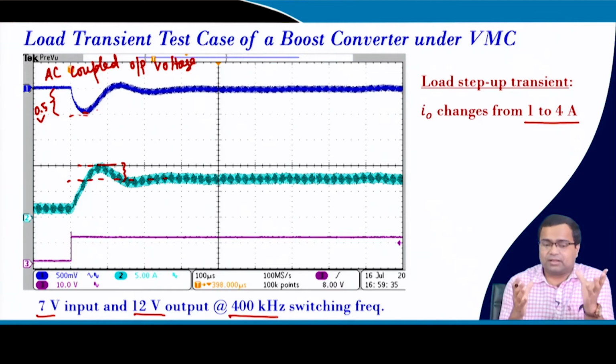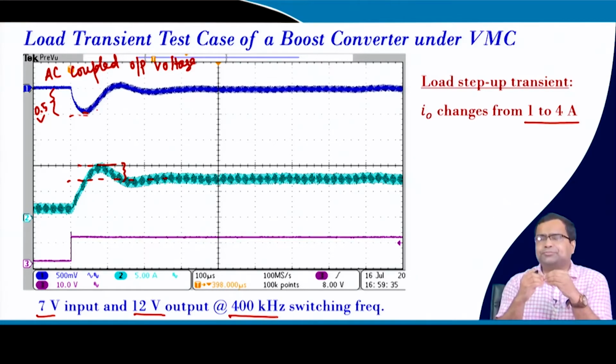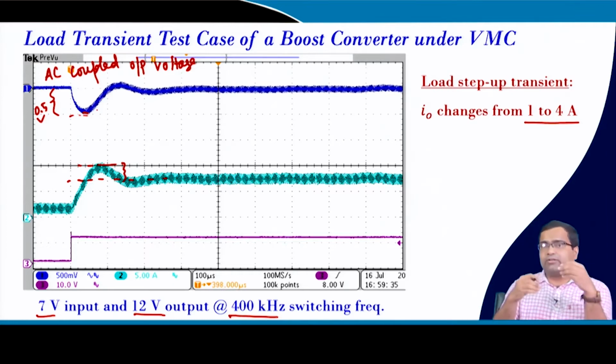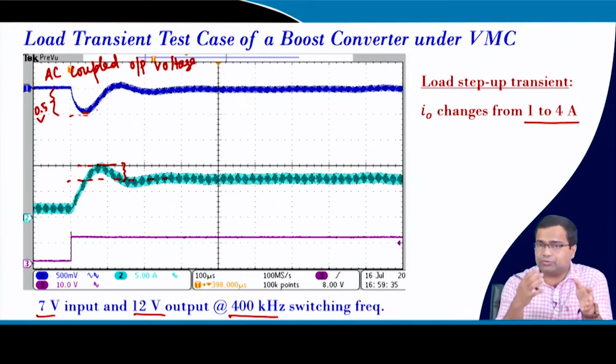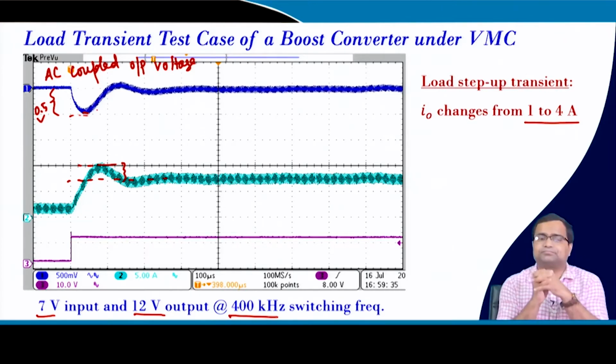This mismatch can have various reasons. Are you taking the right step to measure? If you introduce more parasitics into your converter or in the process of measurement, then the actual converter behavior is different from whatever you are measuring. You should not use a very long cable, and that we have discussed in lecture number 13. So, you have to be very careful about the setup.